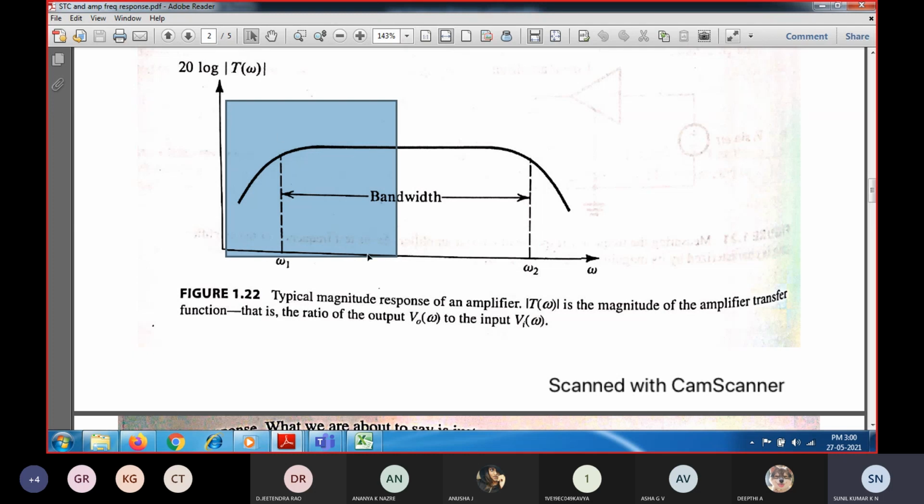If you carefully look at this graph representation, the low frequency response corresponds to the single time constant of which type of network? It is going to display like a high pass type network. In a high pass type network, the low frequency signal will be attenuated and only the high frequency signal is going to be passed. So this is considered a high pass transfer function. Higher frequencies will be allowed, whereas lower frequency signals will be attenuated.